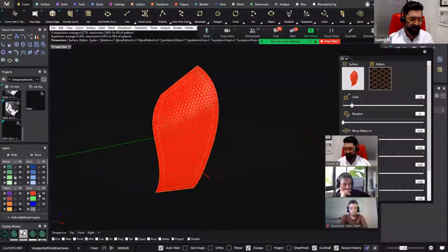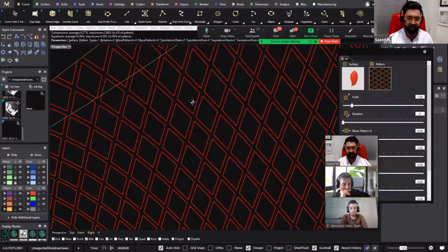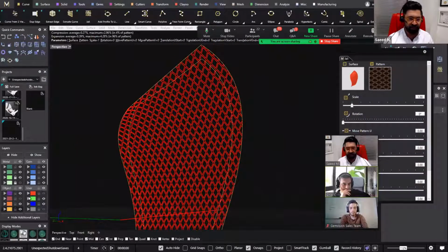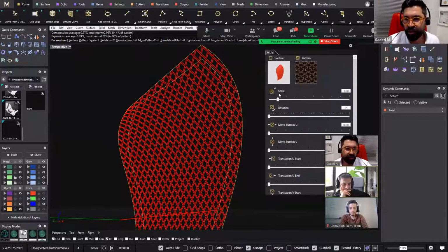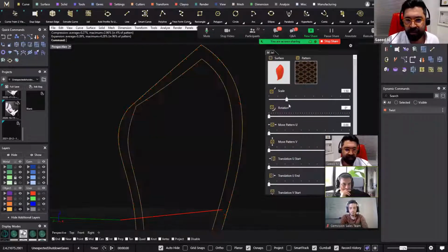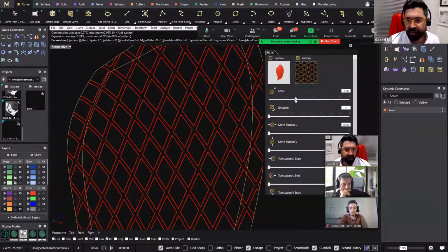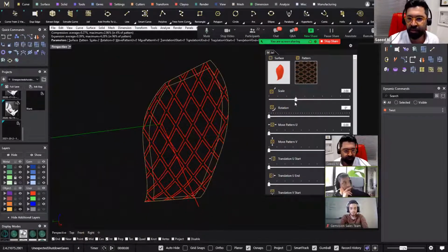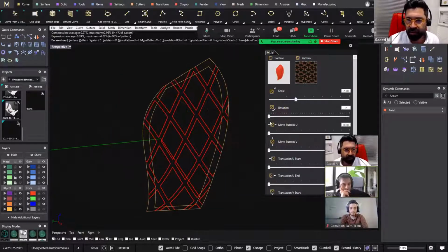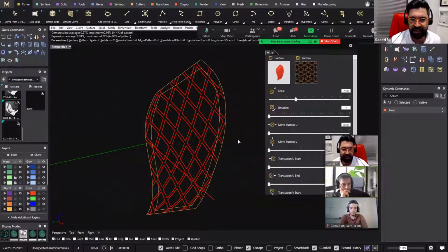As you can see, we have too many lozenges here, rectangular or diamond shaped lozenges. They are very small at first. I'm going to increase the scale option in the Jewellery command. One step more. It's still a little bit small for a ring, and this side looks good for me, or even this side is good for casting. I'm going to select this one because it's a little bit more beautiful and hit enter.